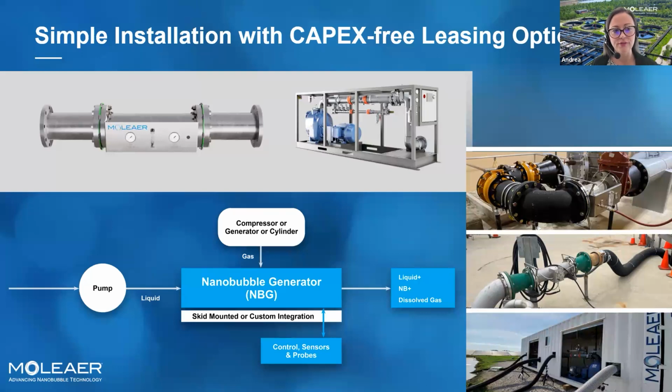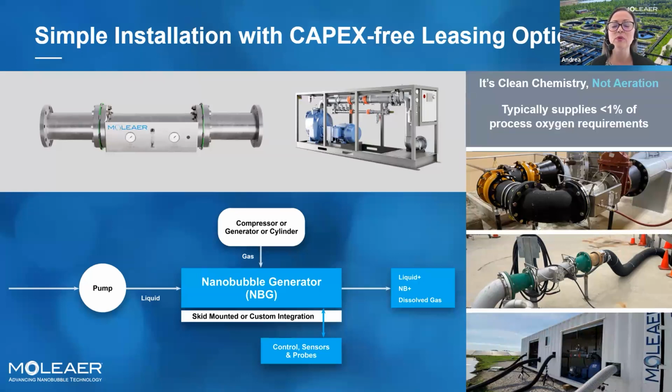We have customers that have found a lot of value in utilizing Moleaer's technology to assist during construction to maintain plant operations and compliance. Ultimately, it's important to remember that this is clean chemistry. Nanobubbles are fundamentally different than larger bubbles. They do transfer some oxygen to the water, but when we're treating wastewater, it is not an aeration technology. Typically, a system like you see on your screen will only supply about 1% of what the process oxygen requirements are.